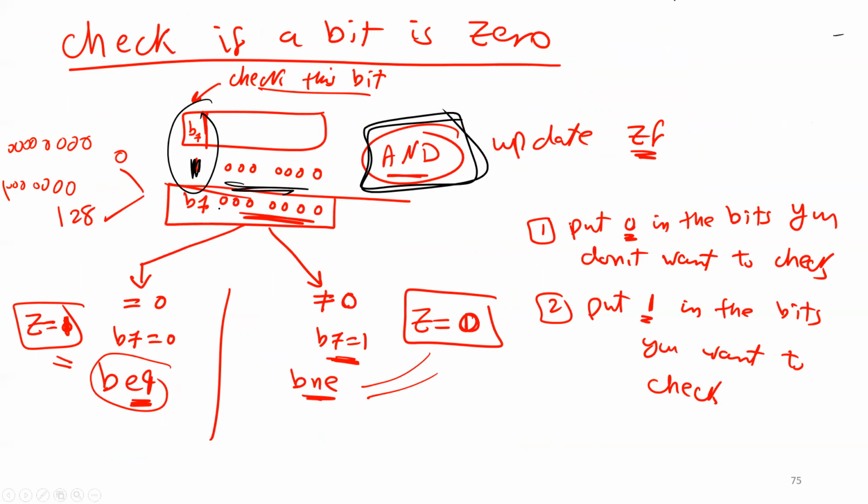Is that okay? Now I want to make a quick revision on branch if clear, branch if set, okay? Because this is the other alternative. So we have here, as I explained before, branch if clear. And then you have to tell me which memory location. So you have to give me an address here. And then you have to give me a mask. And then you have to tell me where you want to go. Like, for example, next. You remember when I explained it this way?